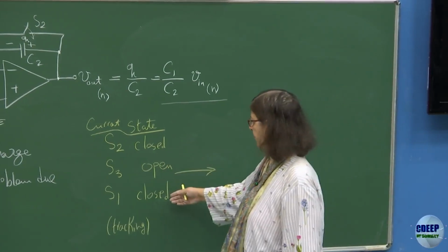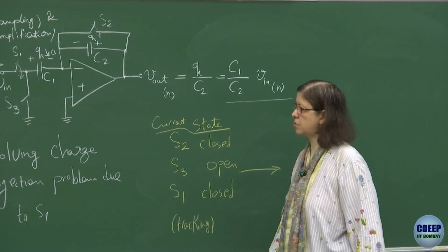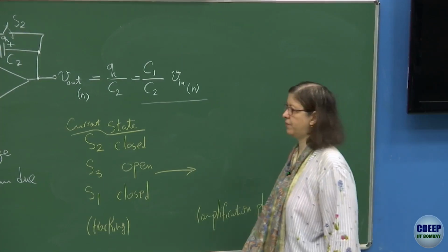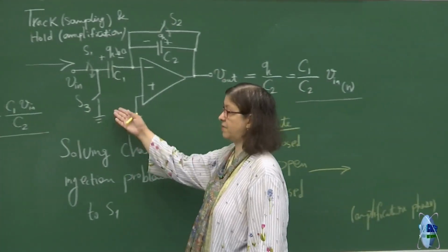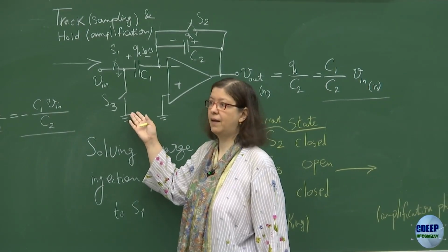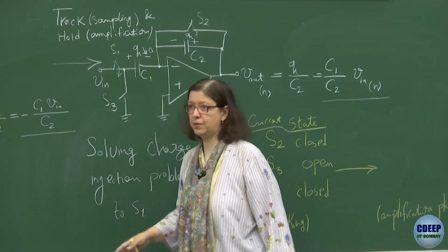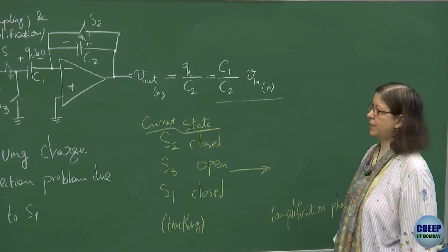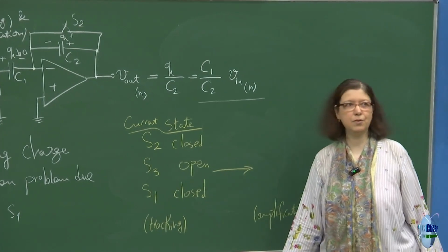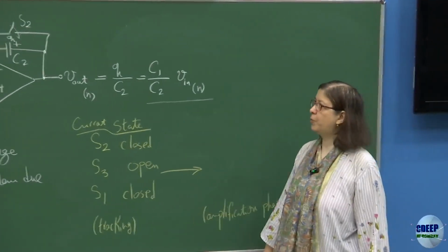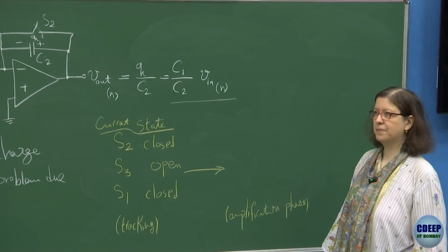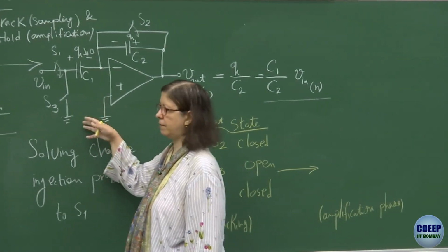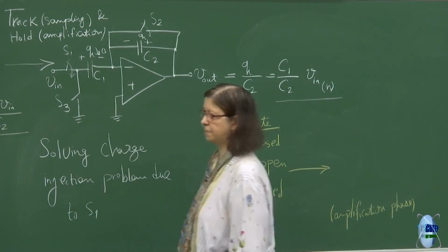Those which are closed should be opened, and the one which is open should be closed. Which one should turn off first or turn on first? Can I, for example, turn on S3 first? Exactly. You would be shorted to ground. That's for sure. You cannot do that. So fine, S3 comes later. What about S1 and S2? Which one should be opened first? S1 or S2? Yes, of course, that can go away still with S3 later.